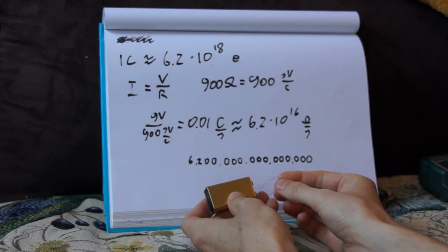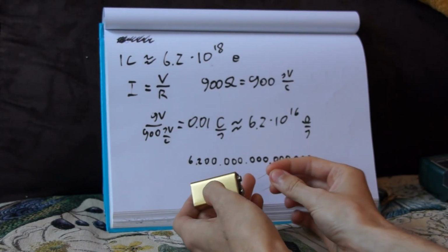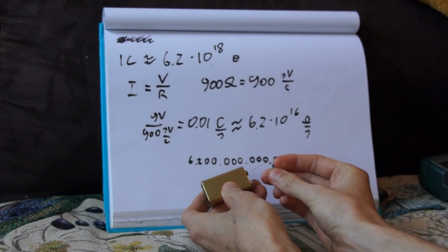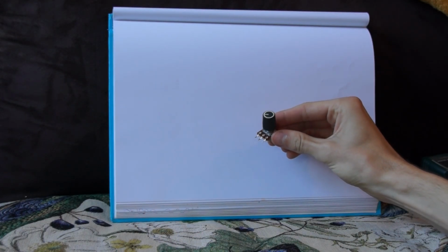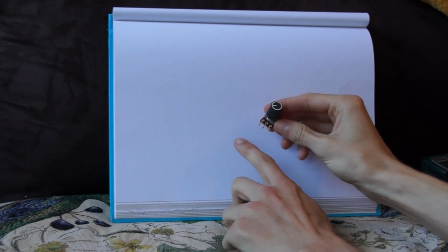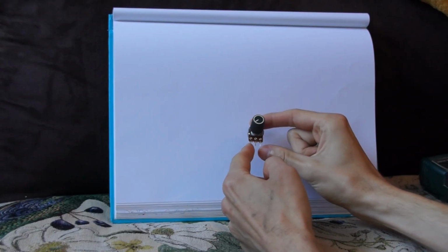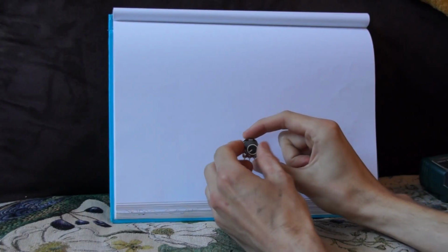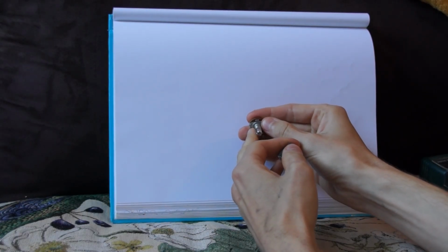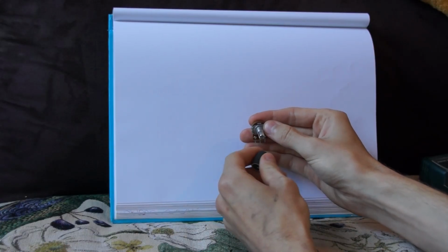The electrons themselves don't move that quickly though. It's just the flux of electrons going through every part of this circuit. Next up, let's talk about these potentiometers that you see everywhere in audio effects. They have 3 pins. The pins at the edges are just connected through a resistor. In this case it says 50K, which means it's a 50,000 ohm resistor.